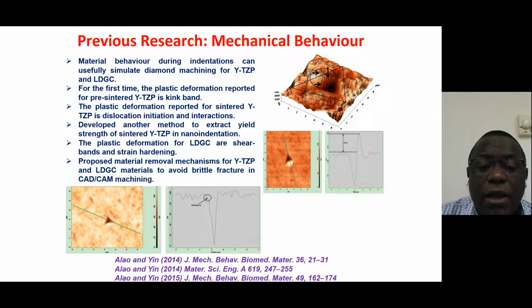So in order to combine all these particles together, forming a microstructure, we are going to use a sintering process at around 900 degrees centigrade. That sintering temperature is the one which gives it the name presintered zirconia. Now, after subjecting it to higher temperature, the presintered zirconia becomes sintered zirconia.